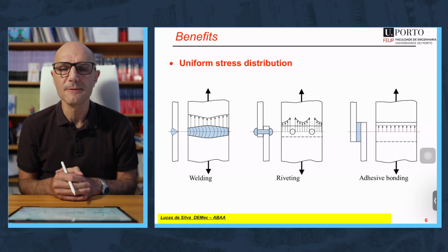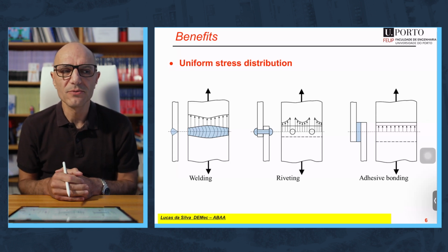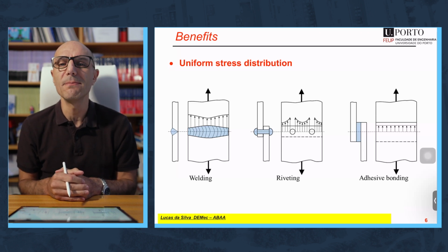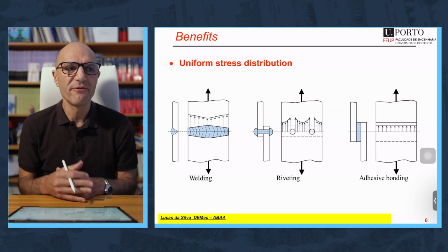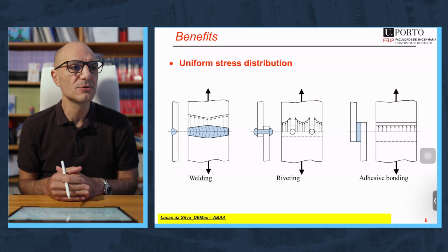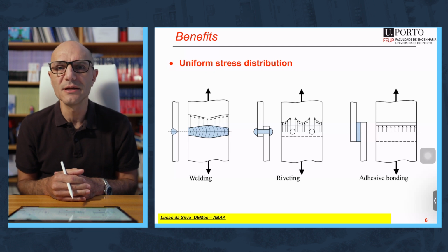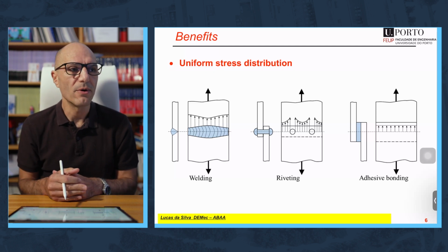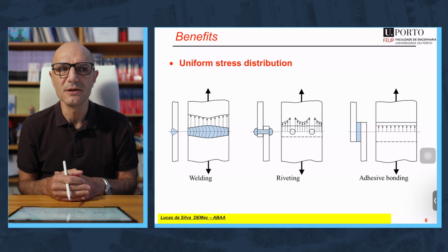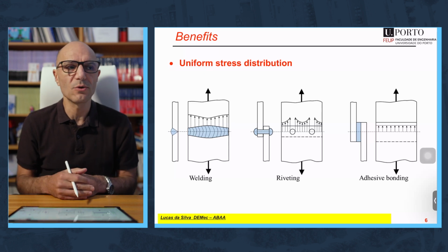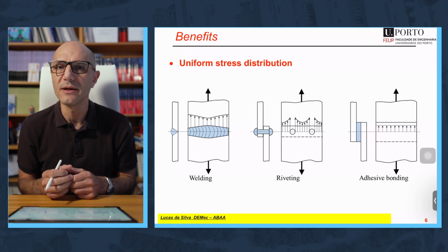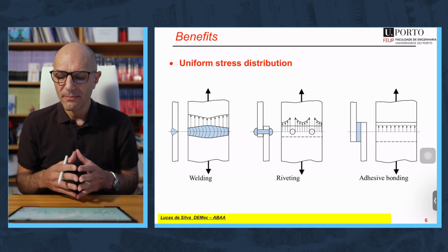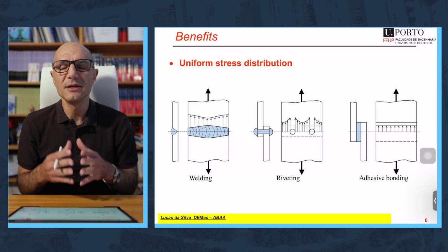It was for me, at least at the beginning, because I was told you have a material that is very weak, maybe 10, 20, 30 MPa, and that is used to bond a material like high-strength aluminum of 500 MPa, or that is used to bond high-strength steel, which is 1000 MPa, or that is used to bond composite materials that can be 1000 or 1500 MPa, but still they are used. Does it make sense? Not really. It makes sense, however, if you use properly the adhesive in the joint.